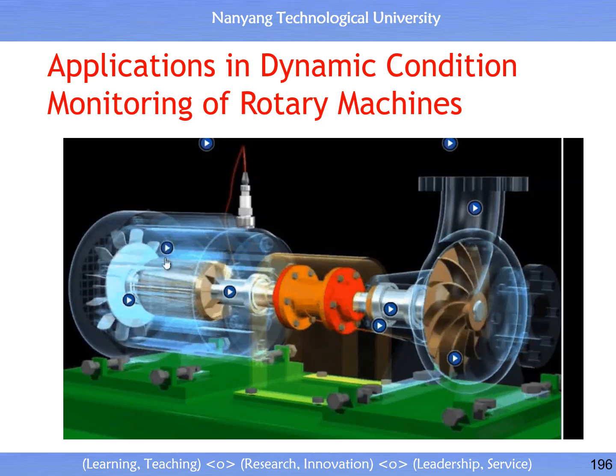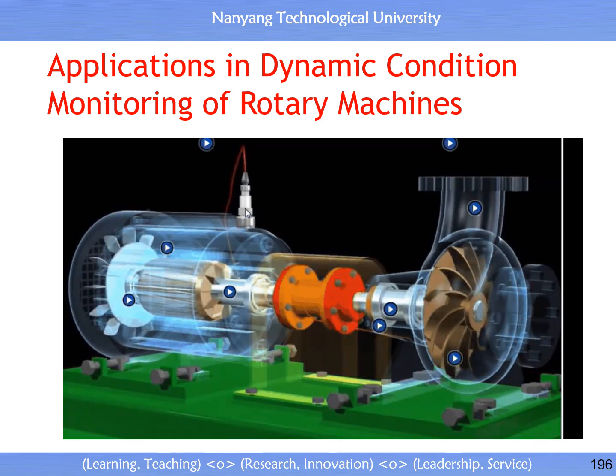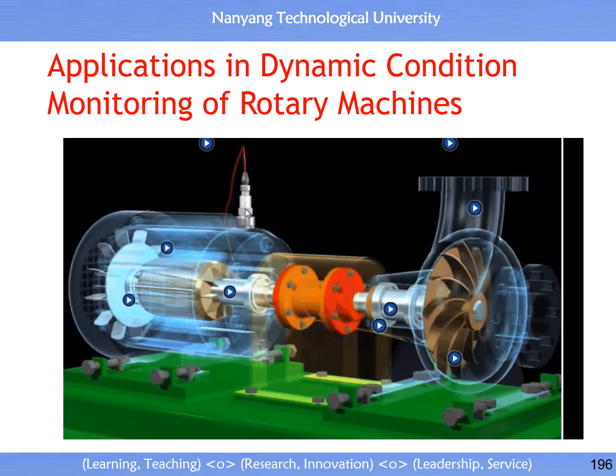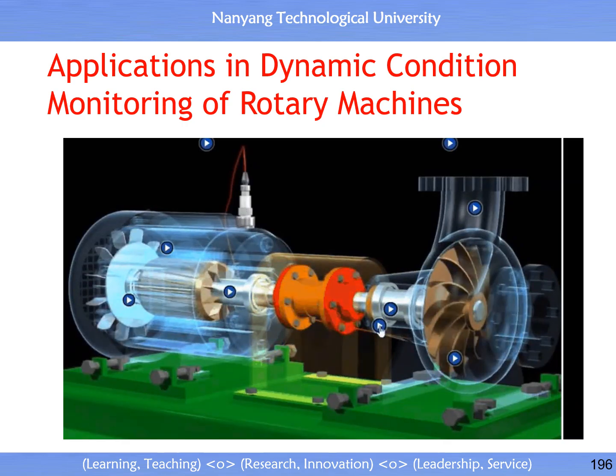Now we pick up all those sounds from here. They all combine together into one measurement, but separating them in frequency and some of the other things we'll explain let us do that so we get an idea of the health of each of those components. Over this side, that bearing is not in good condition.